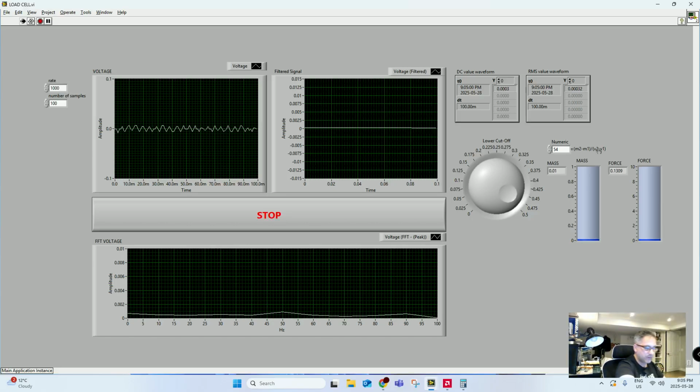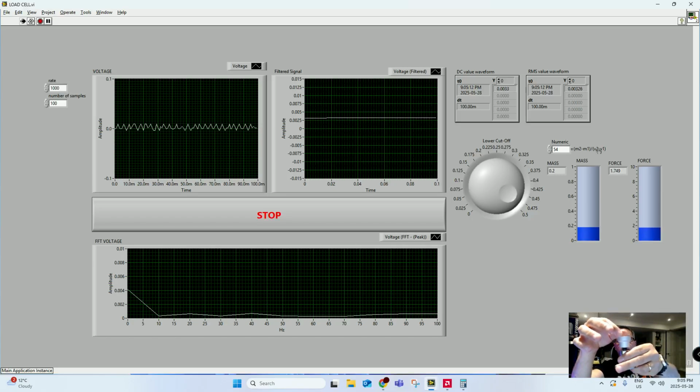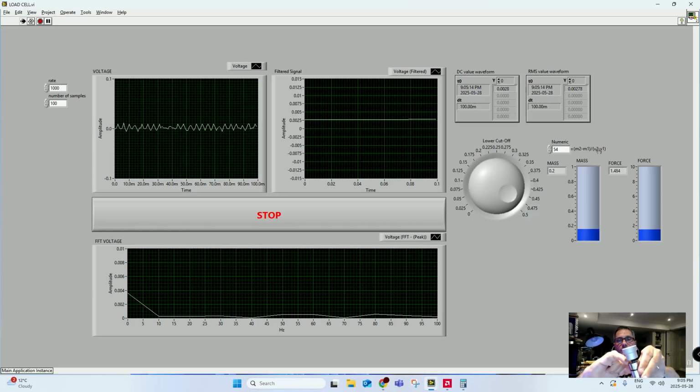When you assemble this load cell, the signal is going to be completely disoriented. It has been assembled with this counter nut that pushes the support up without altering the plate where it is sitting. Because if you remove the jam nut and tighten this part until it is flush with the top of the surface, you basically deform the strain gauge where those are touched. So by the time you screw, you will alter it.